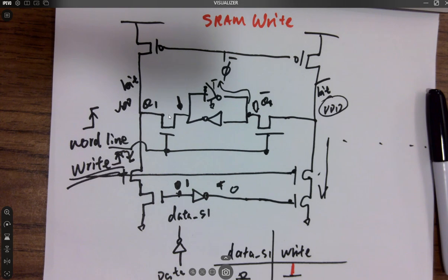So the conclusion is that you synthesize your digital design using Verilog and certain tools, but the memory has to be designed and compiled by a different tool. That tool is called a memory compiler. The memory compiler uses a different library which has all these SRAM cells.